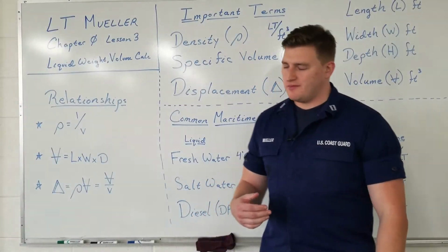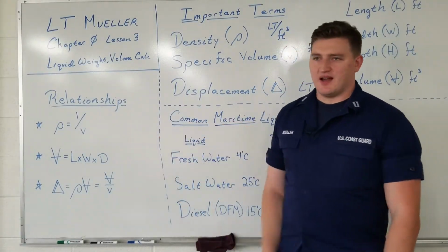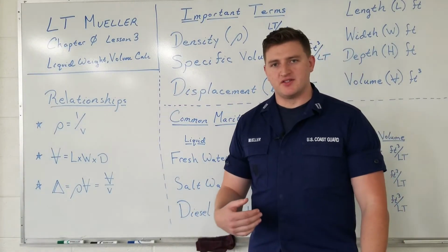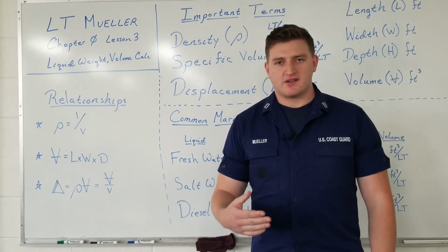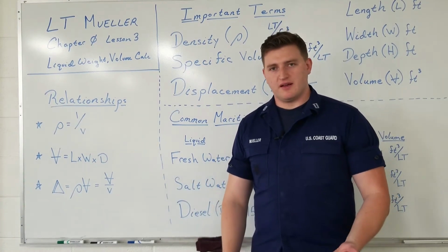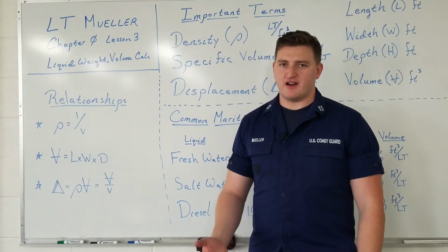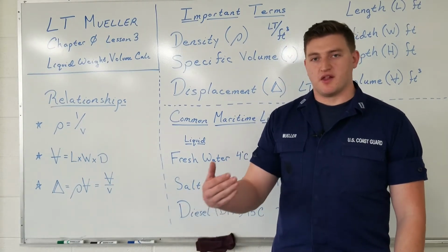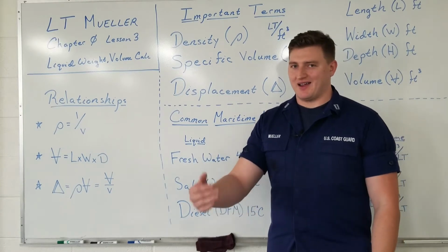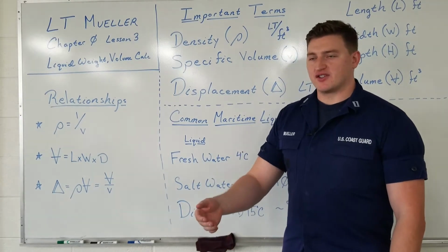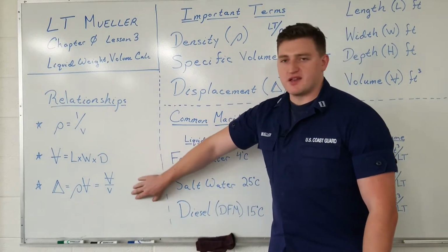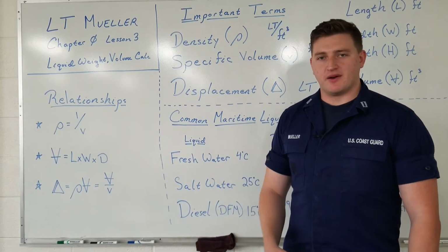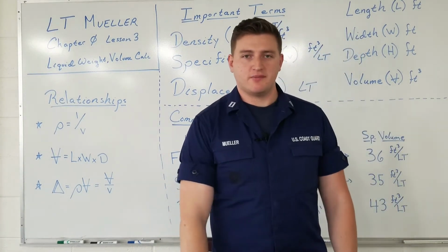Throughout this course, we're going to be using all these relationships in the context of ships taking on damage, whether it be hitting rocks and then flooding compartments, or if they are fighting fires, you have to use firefighting water which comes out of the ocean, which means that you're adding weight slowly over time, typically high, which means that you could be affecting your initial stability. These volume and displacement calculations are going to help us determine if we're harming or helping the initial stability.